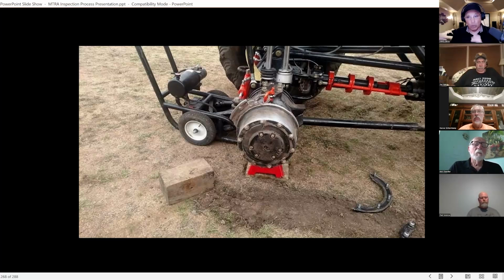When lug nuts get loose, let's say they don't strip, they just get loose, that movement will load the flange on a Clark. A Clark has an inherent flaw, and that's why CRD makes aftermarket hubs for them that are really expensive, but it's because of this failure point. And there are also girdles that some teams will use to support this flange.